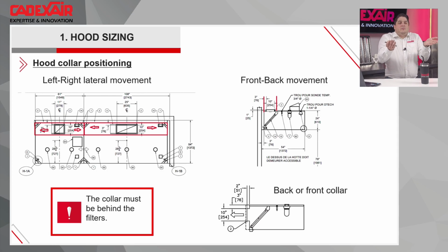And after that, the left side of the hood is full and it leaks by the front. So I said, yeah, that's not really fun because we have a lot of filters on the left. So we just opened a hole inside of the hood, and it allows the smoke to go to the other side to solve the problem. So it helps to contain. The bigger the hood, the bigger the containment. Nobody cares if your smoke is taken by 3 filters on the left, 2 filters on the right. They just don't want to have the smoke in the face and the smoke in the place.